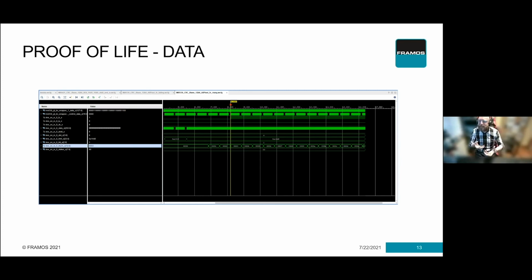And what that means is that any kind of issue with the amount of solder that's in there, maybe let's say you've got the reflow machine and one side slightly colder than the other, and that's the side where you'll get lots of failed devices. That's because the temperature isn't hit. You also have it the other way, where they just unfortunately stick everything through at 220 degrees, and suddenly your image sensors have defects as well as issues due to that heat.